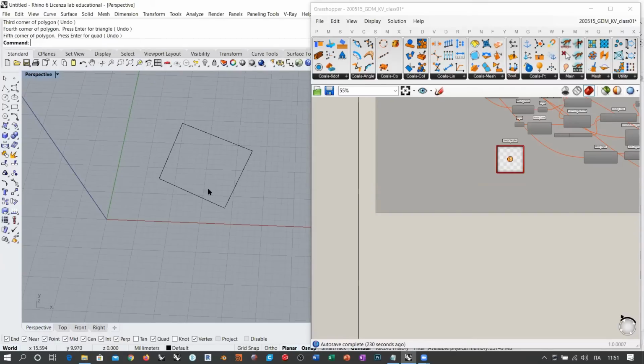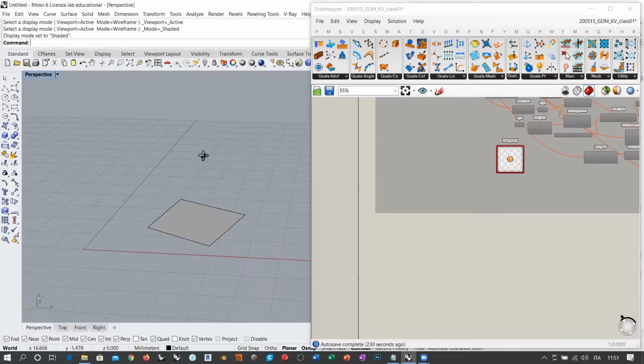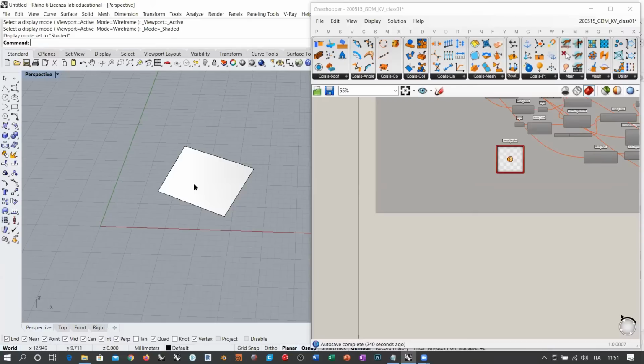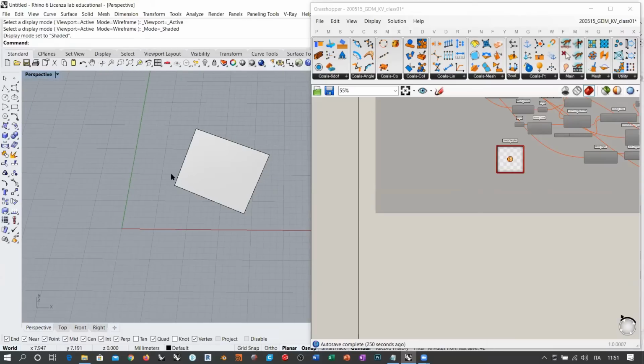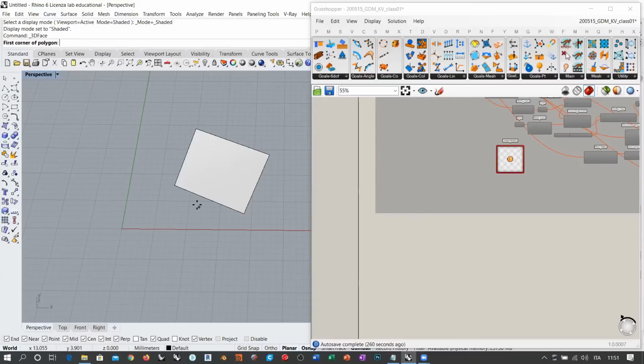Just consider that you always need quad faces. Actually, it doesn't matter exactly the orientation, because once we join them all together into one single solid, all the orientations would be flipped with positive normals pointing outward. So you can also avoid considering the orientation of your initial polygons, but I do recommend that you always take the orientation into account.